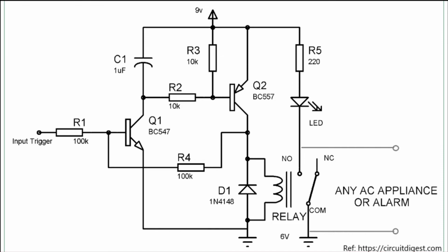Now, coming to the functionality of the diode in the circuit, that means this diode D1, which is known as 1N4148. It is used to prevent reverse current flow when a transistor is switched off. Every inductor coil in a relay produces an equal and opposite EMF when switched off suddenly. This may cause permanent damage to the components, so a diode must be used to prevent reverse current.